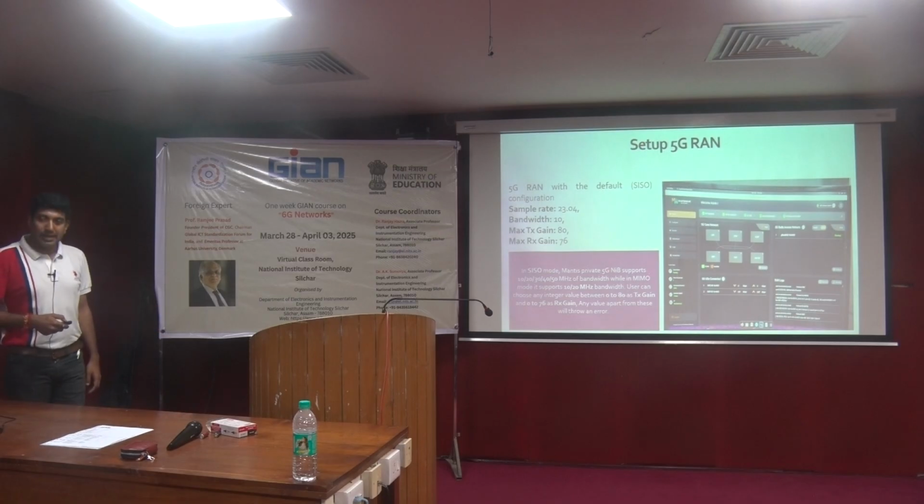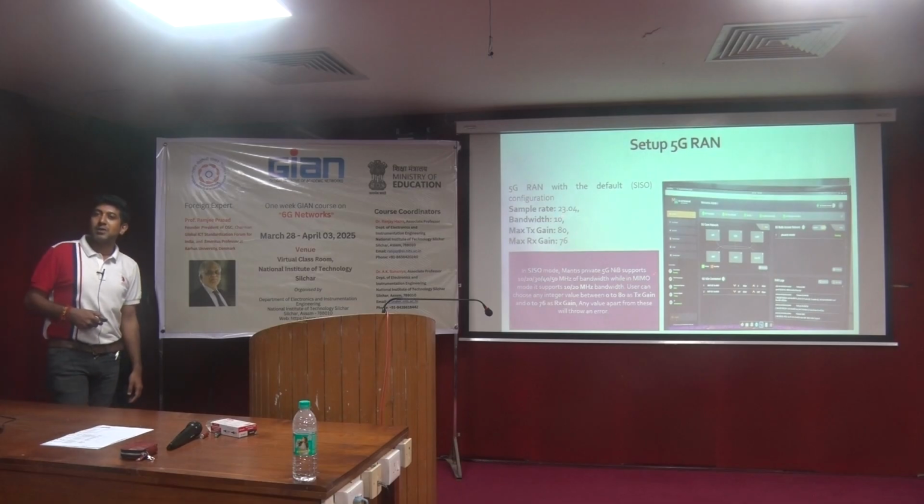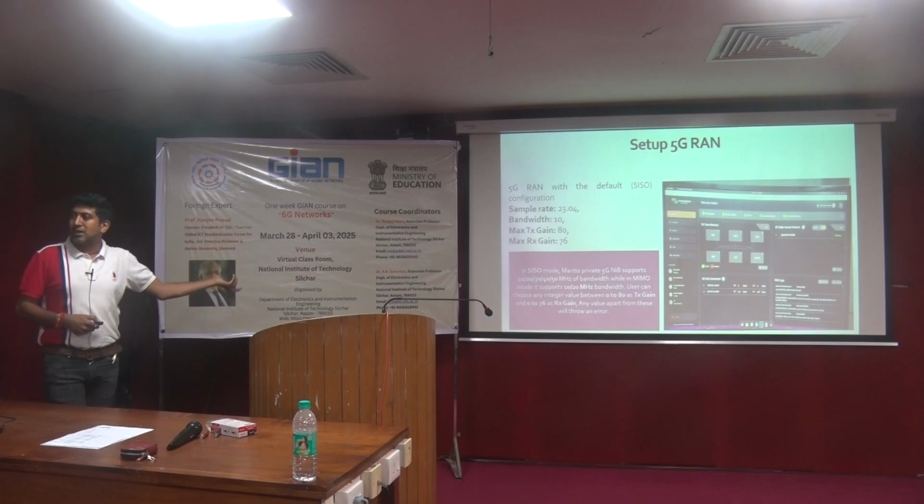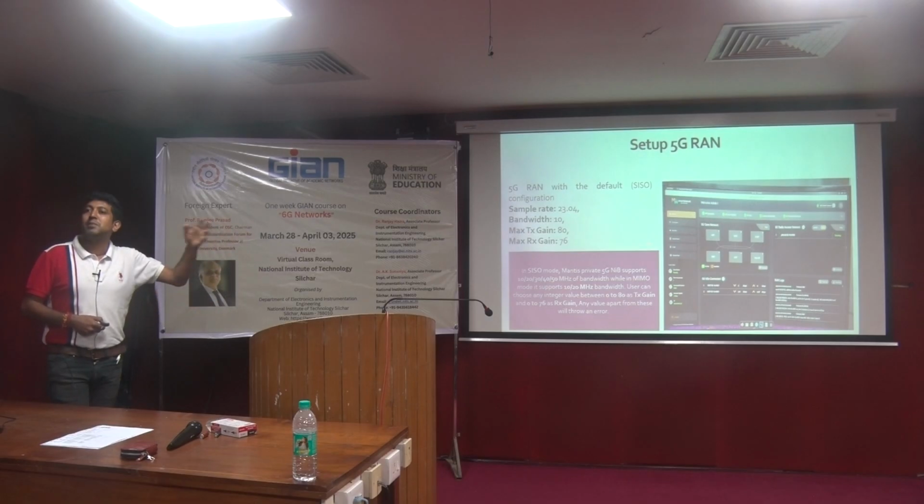Okay. And as you know, if my sampling rate is 23.04, इसका मतलब क्या? What is your message frequency? It is less than twice that value. So obviously it must be some value which is less than 11 megahertz, maybe 5 हो सकता है, maybe 3 हो सकता है, depending upon what kind of information you have.